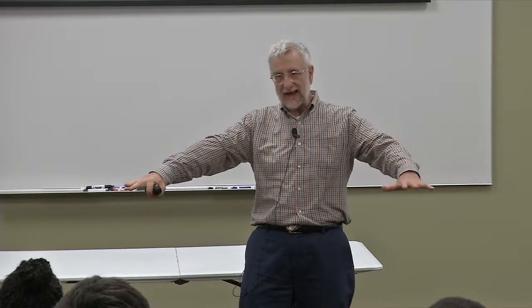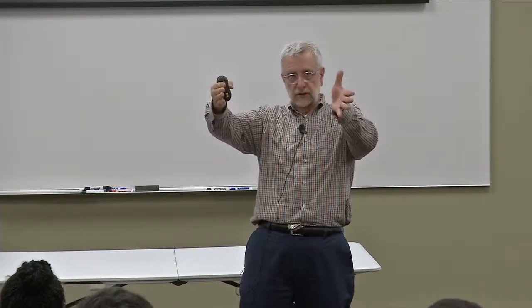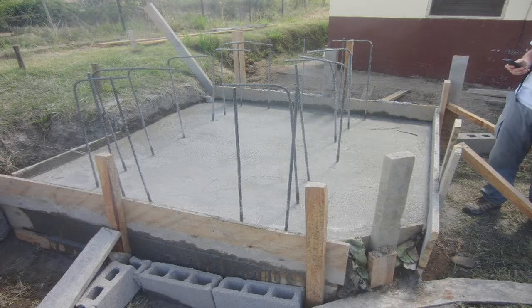You'll see what I'm talking about here. So basically, you've got a mat foundation, and then you've got another rectangular projection of concrete up that becomes the pedestal, and that's actually what it sits on. And this is designed to carry any bending that might be in the concrete, as well as to handle the shrinkage problems.